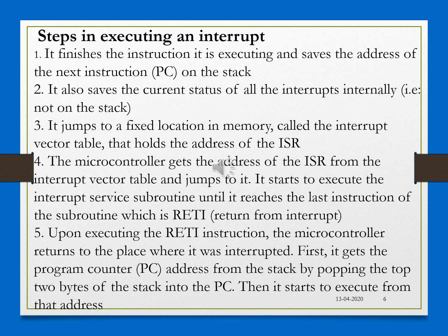The execution of RETI means: pop the 2 bytes of address that were saved before execution of the ISR and load them back into the PC. So the PC will go back to the location where the interrupt was encountered, and it starts executing from that location.